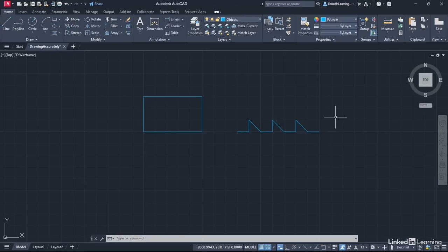Another typical one might be you've got flowcharts to draw. Really useful if you use those regular shapes on the grid and snap to the grid to draw your flowchart symbols. Now, there's a lot of ways and means of working with this, but you can use circles and arcs as well. So if I go to a circle command, let's do center radius. If I pick that intersection of the grids there and come out, as I come out, can you see each grid square is making the radius bigger?